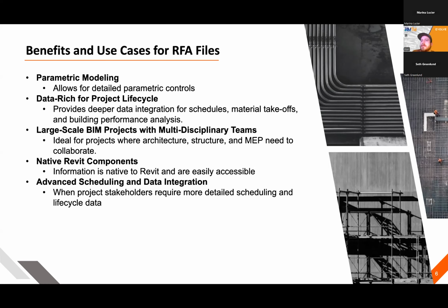So physically connected together. But that connection between other objects can also be things like flow calculation between two fittings or the rest of the system. You could take it one step further, and you can also link cut sheets to those fittings or reference material specifications. So again, just the connectivity with the parametric ability with RFAs and ITMs to an extent, but RFAs being extremely parametric when it comes to all things in the project.